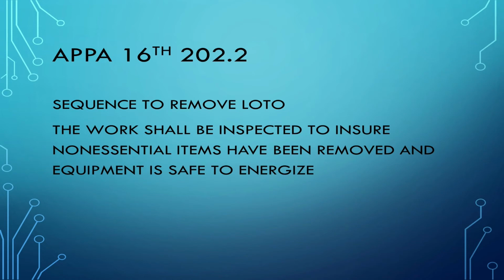If everyone does the correct procedure, gets their own tag, so that when they go by a control point that another crew is tagged, if they get their own tag and go through the process according to the OSHA and APPA manual, then dispatch is going to be aware of where everybody's at and what they're doing. So it's very important company-wide that for lockout tagout to protect us, we are going to have to follow rules and procedures and be diligent about getting our own tags and the same person that got the tag relieving the tag.